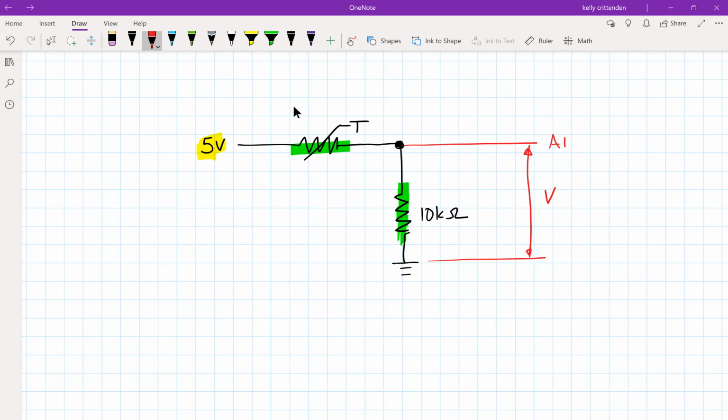And we're doing it that way because we're using NTC style thermistors, so that's negative temperature coefficient. So their response is inverse from what you would want, basically. So in other words, temperature goes up, the resistance goes down. So they don't have a positive temperature coefficient. There are some like that. Typically, the positive temperature coefficient thermistors are used more like a shutdown switch or a fuse or something, where as their temperature increases, their resistance increases.